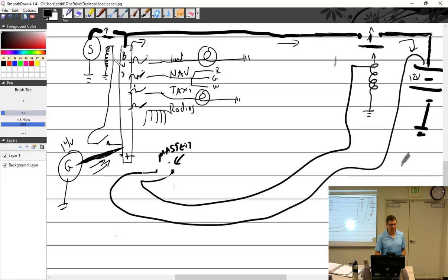Hopefully not more than 30 seconds. So that's a light duty, intermittent duty, we call it, while this one is continuous duty. I don't honestly know the difference between them other than part number. I would just order my part number. If there is a difference, they're going to be made different. It's highly probable Cessna just uses the same one. It's easier to make one continuous duty and sell you that one for everything than it is to make an intermittent and go, well, you should use this here.